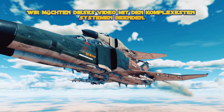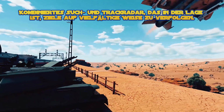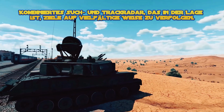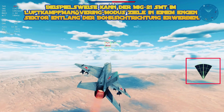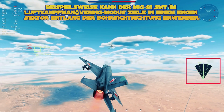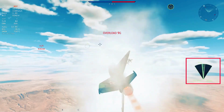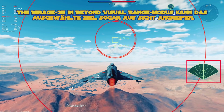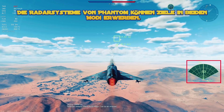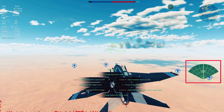We'd like to finish this video with the most complex systems: combined search and track radar capable of tracking targets in multiple ways. For example, the MiG-21 SMT in air combat maneuvering mode can acquire targets in a narrow sector along the bore sight direction. The Mirage 3E in beyond visual range mode can attack the selected target even out of sight. The Phantom's radar systems can acquire targets in both modes.